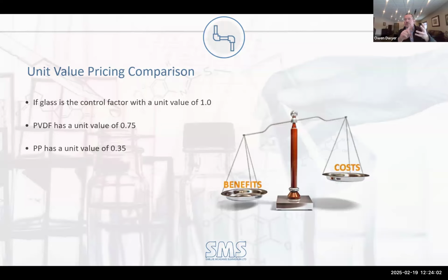And again, checking temperatures, corrosion resistance, building limitations, etc. Polypropylene is your most cost-effective application. And you can see why duriron is no longer made. It was 3.5 times that of glass, where now in today's market, it would be 10 times more costly than an equivalent project in polypropylene.